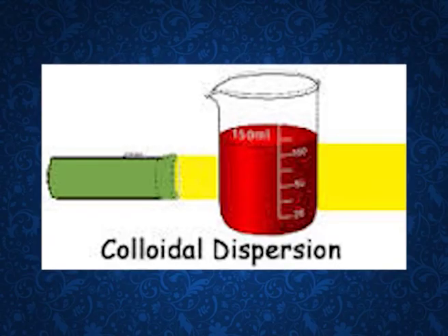The binder is dispersed in a carrier which can be water or an organic solvent, either in molecular form, that is true solutions, or as colloidal dispersions, that is emulsions or sols. Then come the pigments. Pigments are generally colored inorganic substances that are ground into a fine powder and suspended but not dissolved in the binder. Pigment is actually insoluble in the medium in which it is dispersed. That means the pigment granules remain intact, do not dissolve, and get dispersed across the surface evenly.